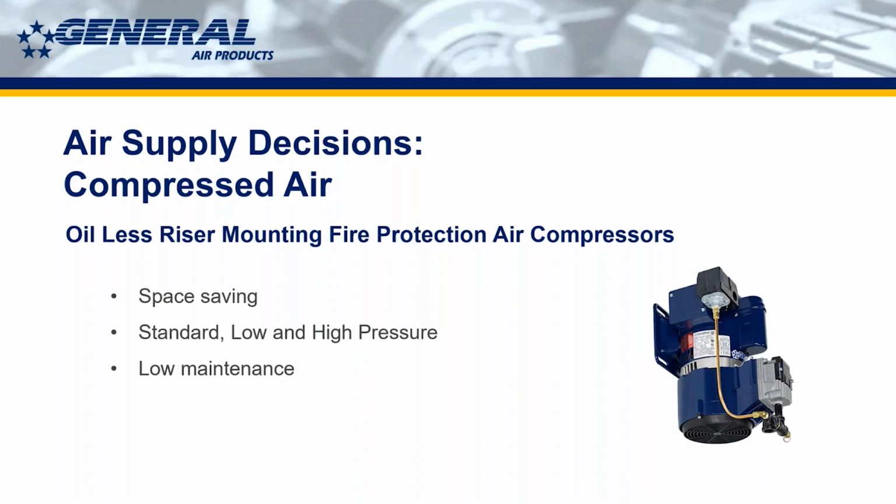Now, oilless, as I said before with maintenance, every unit needs maintenance. So oilless is low maintenance, not no maintenance. Please be sure to check in on those. They can be neglected a little bit more than the lubricated compressors, but at the same time, they should be looked at on a regular basis, just to make sure they're anchored properly, all the fittings are tight, and it's operating the way that it should.